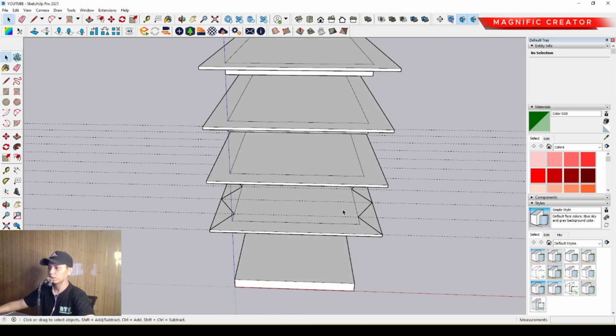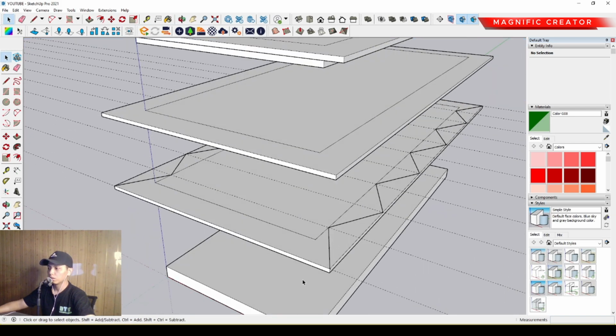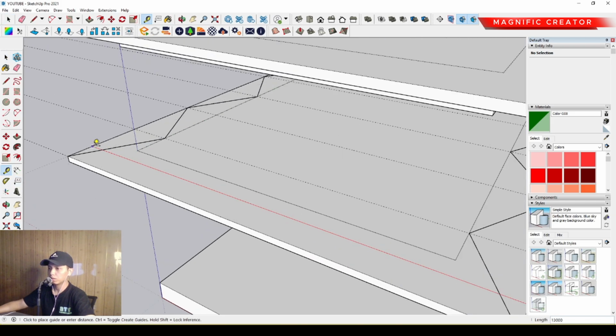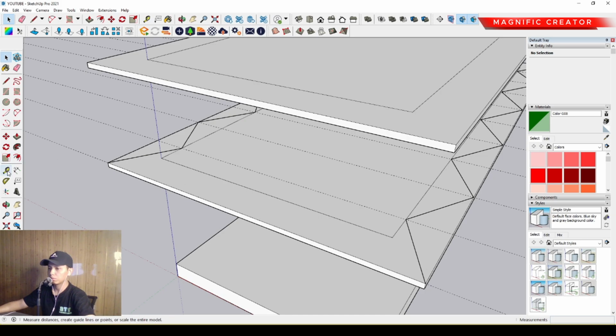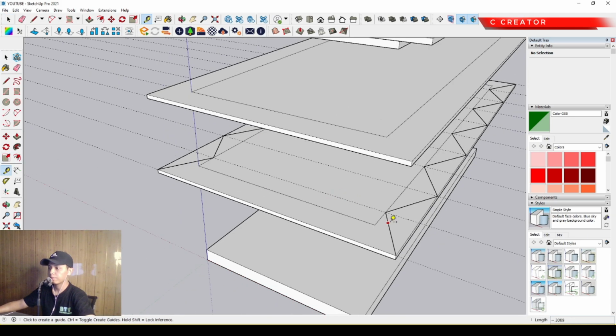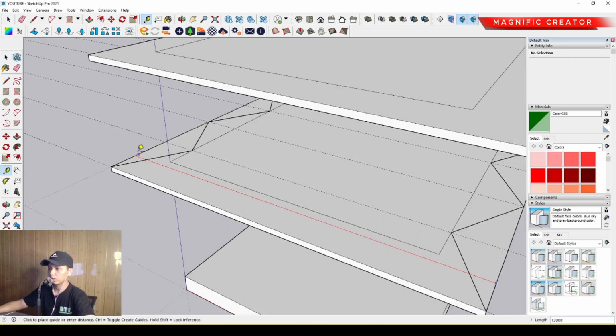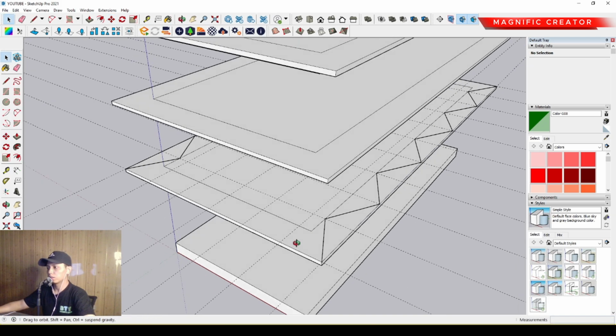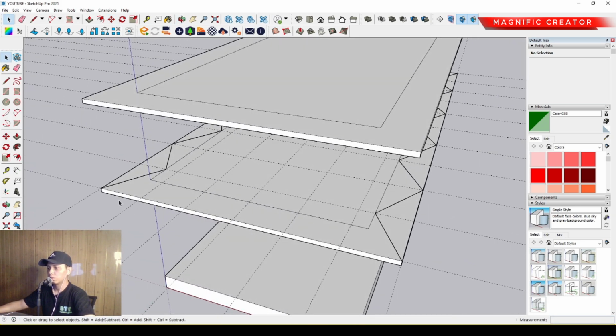Then we can set the longitudinal arrangement by using the tape measure tool again. We can place it here. If you want to use the tape measure tool, you have to select this and click from this, and just click to this. Then we can duplicate by selecting Control and placing it. Then we can divide, typing 6 slash and enter, so it would be an automatic arrangement.